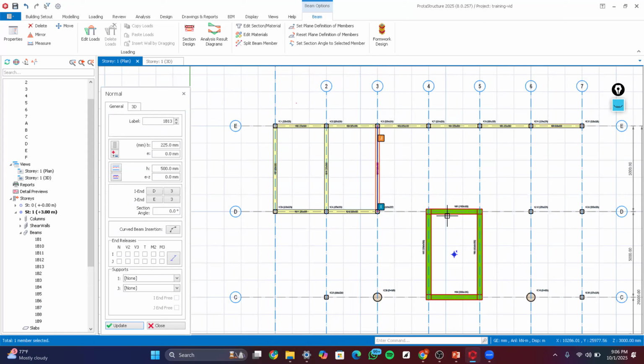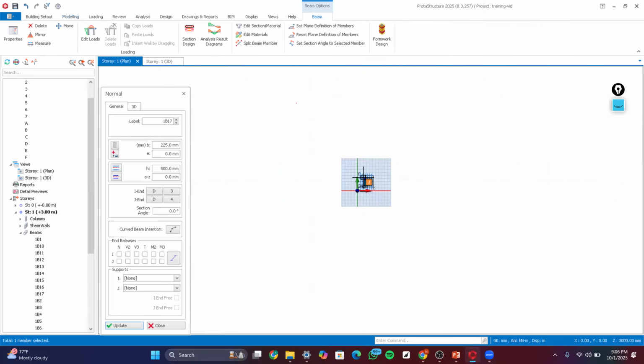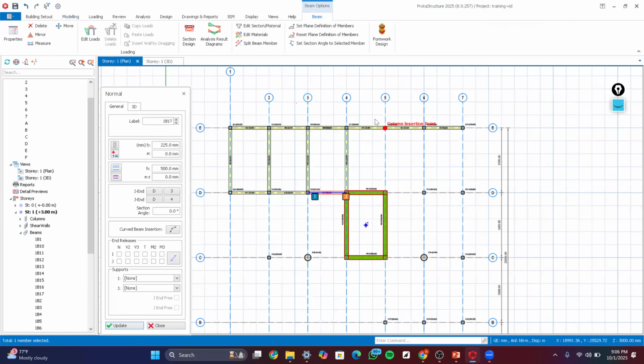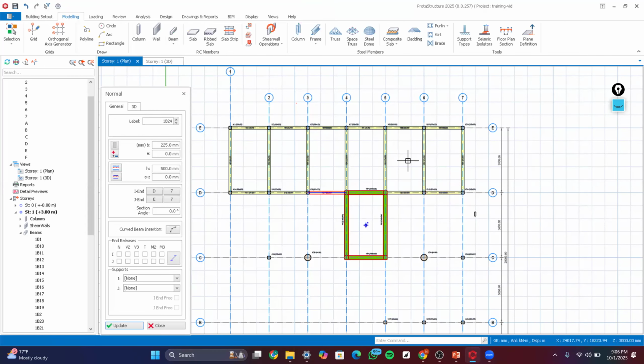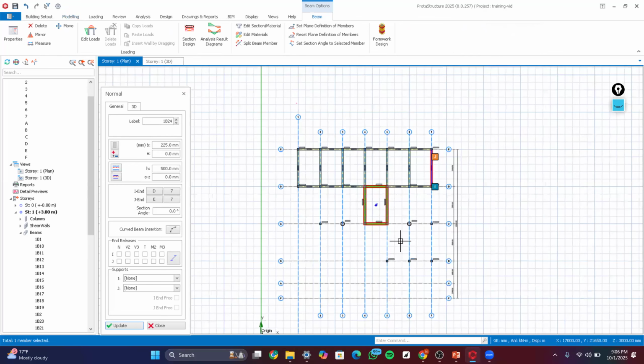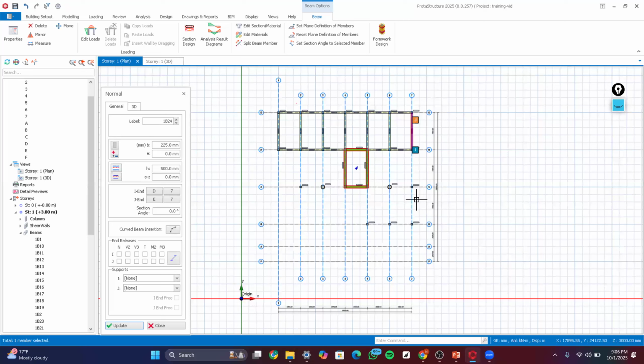And let's continue. So please bear in mind that your beams cannot be created where we already have walls or where we already have existing beams, because your walls are actually self-supporting. Okay, so beams cannot be created where we have existing walls or existing beams when we are using that cross selection method to insert our beam.